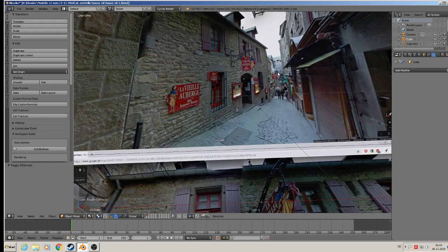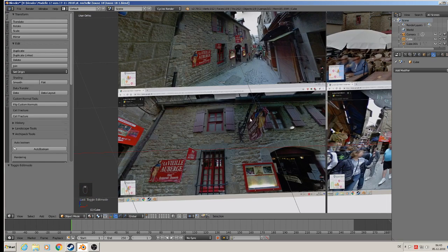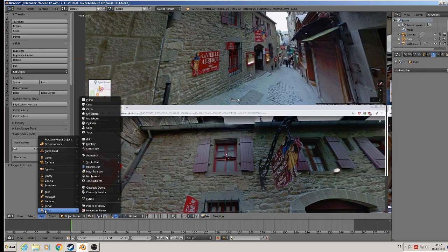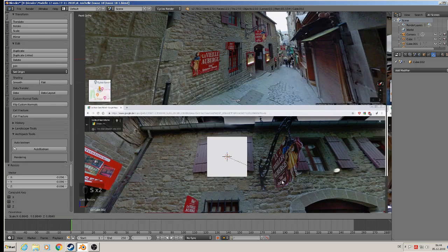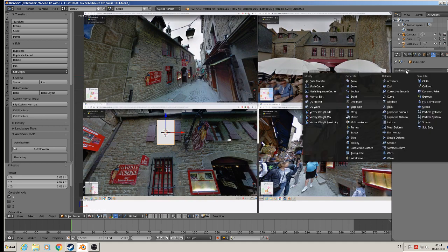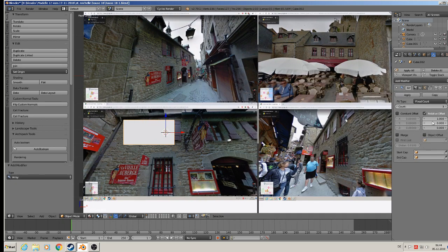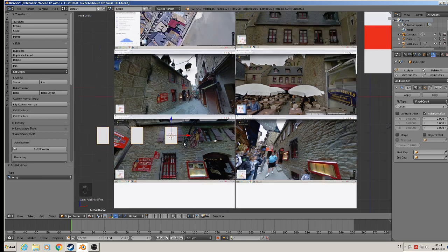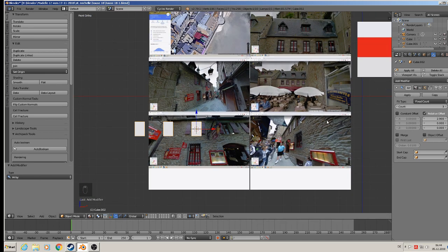You see there are 3 windows on the top, so we plug them in too. So add mesh, cube, scale down, scale set. So I think that is the size that they have, and I take 3 of them, so I add an array modifier, 3 of them, and bring them there. You must calculate that on each side is this part, so you need much space there, so bring them in a good way. Space between. So apply.